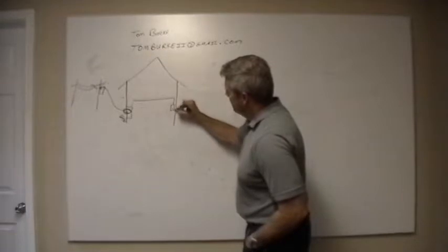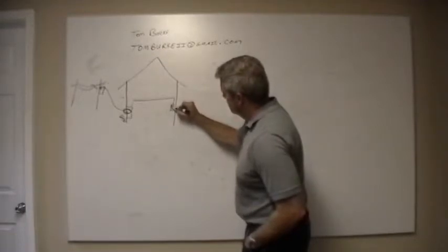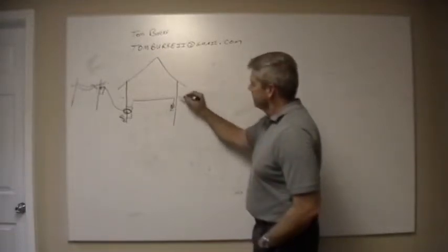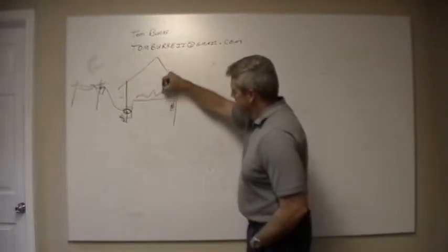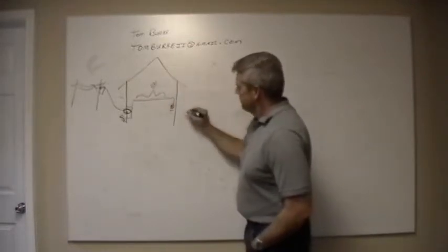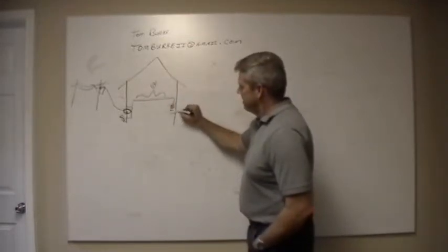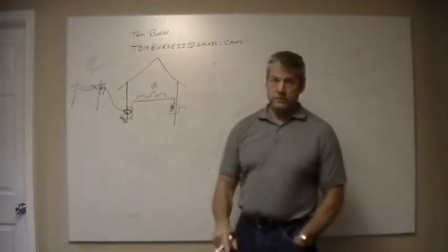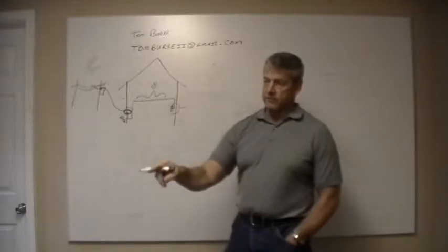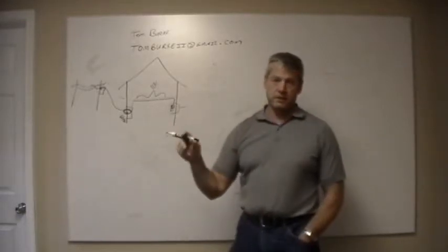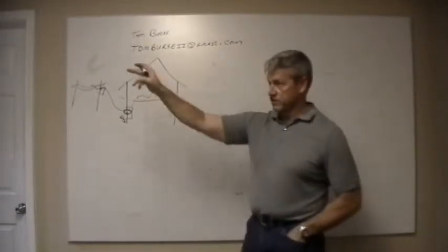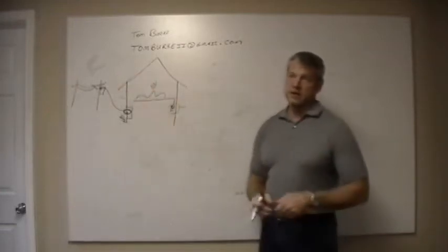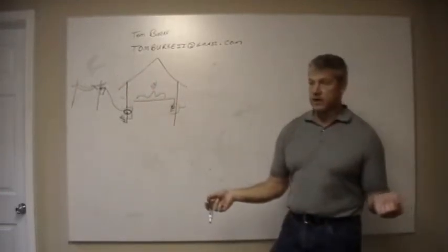To an outlet here, the maximum voltage drop is 10 volts. So that means that at any outlet under the full load allowed for that size of wire and current, whatever. So if you've got a 15 amp breaker, it's got to be at least 14 gauge wire, I think.